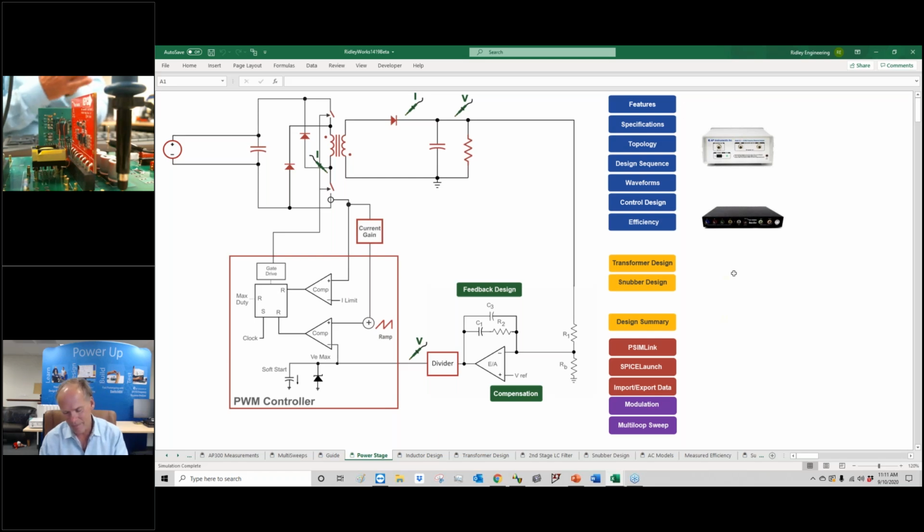So what else limits it? Well, the control chips. It's hard to get a control chip that's happy above a megahertz. If you're using a micro to control, you have to make sure you have the resolution. But the gains you get above a megahertz or two start to diminish fairly rapidly. You just have to look at the Vicor products to see that. But you can keep going with the flyback. It's a good question, actually.